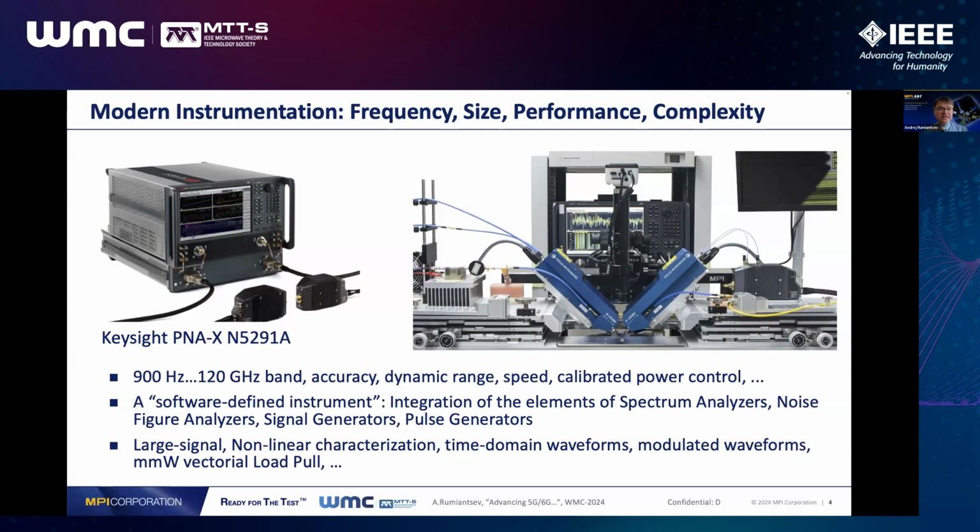Having just a vector network analyzer, you can also do a lot of other types of measurements. This instrument has integrated elements of spectrum analysis, noise figure analysis, signal generators, pulse generators, and so on. And we can perform large signal, non-linear characterization, time-domain waveforms, modulated waveforms, millimeter wave vector load pull system, and many others. As an example, you can see an integration of such a system with the Focus Microwave and PNS tuners on an MPI system, where we can do large signal characterization up to 110 gigahertz. So the complexity of the measurements that we can do today at the wafer level